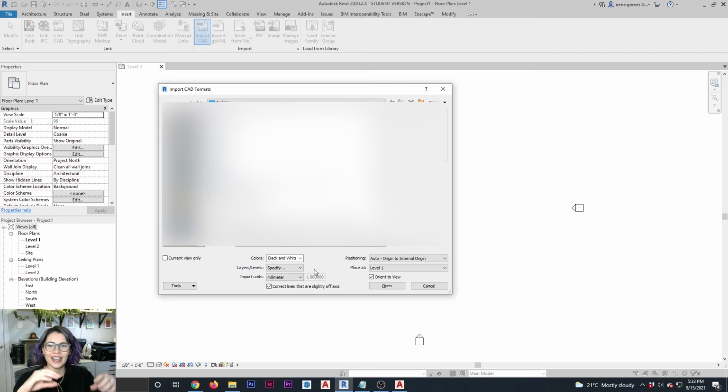They're just slightly crooked. And that slight crookedness can really ruin the quality and precision of your drawings when you start building them in 3D. So again, an absolute nightmare when you're working, for example, in SketchUp. Thank God, in Revit, it has an option that automatically fixes that problem. So again, by default, it's checked on.